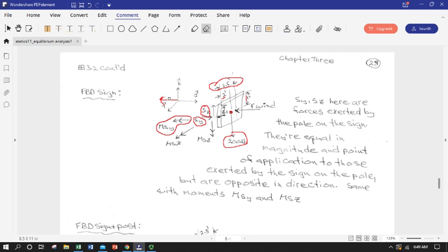More importantly, we're going to need to counteract a twist. So this wind load is going to want to make the post twist around the z-axis, like so. Twist it straight around. So the post is going to need to apply a moment to prevent twisting around the z-axis.